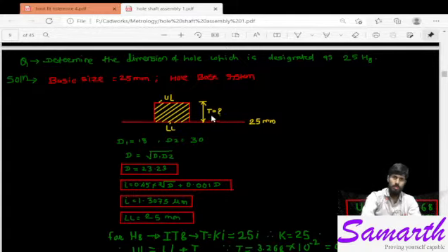Now, as this 25 falls in the range of diameters 18 and 30, D1 will be 18 and D2 equal to 30. Recently we have seen that table. Here we have got the value for capital D. This will be in millimeter. By putting this in the formula as it is in millimeter, you will get the value for i in micrometer.